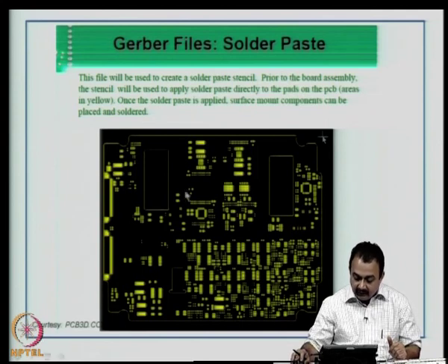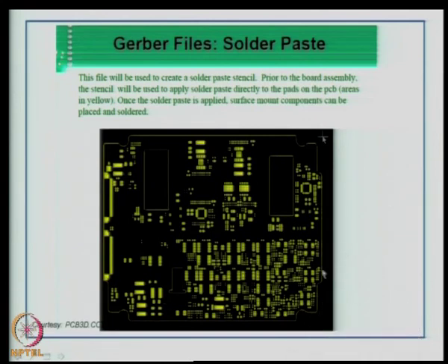So, you can see the openings here, that is the surface pad areas of all the components, on top of which your solder paste will be printed, or it can also be syringe dispensed in very minute volumes, and on top of which the surface mount components will be placed, and then it will be sent for reflow soldering, and that is how the attachment of the surface mount devices onto the surface of this board takes place.